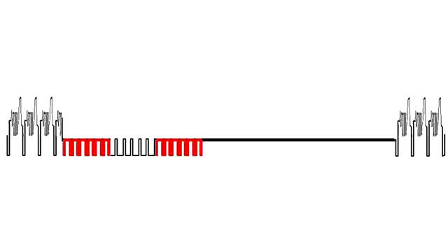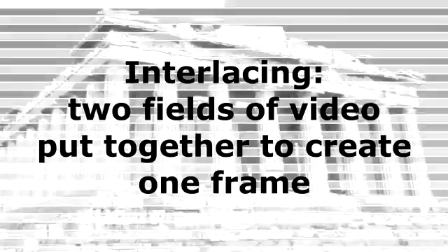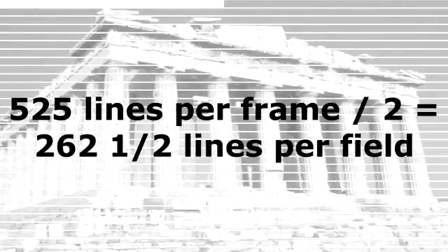The shape of the vertical sync pulse is actually 6 small pulses. It's made up this way to provide continuous synchronization for the horizontal scanning system of the monitor, even during the vertical retrace period. In addition to the vertical sync pulse, another group of pulses is required when using interlaced scanning. Interlacing occurs because the second field of scanning starts half a line's distance across the screen relative to the first field. The analog television system has 525 total lines per frame. Therefore, each field has half that many, or 262.5.